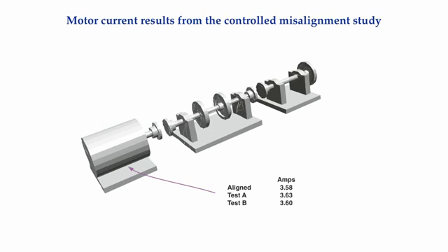So, to summarize the results of this experiment, I suppose we can say that the vibration levels decreased when the drive system was misaligned. The center shaft appeared to elastically bend, and the amount of elastic bending increased as the misalignment increased, and there didn't seem to be much of a change in the power requirements to operate machinery running misaligned.